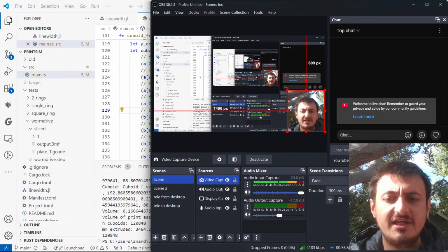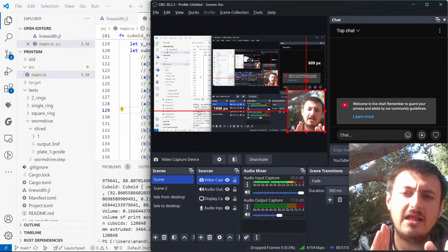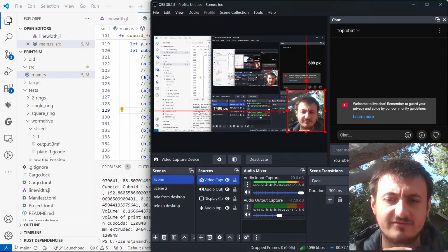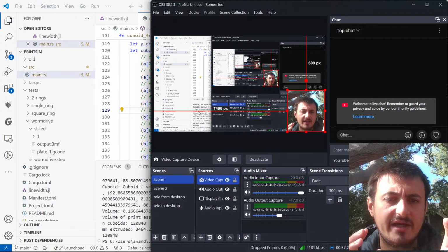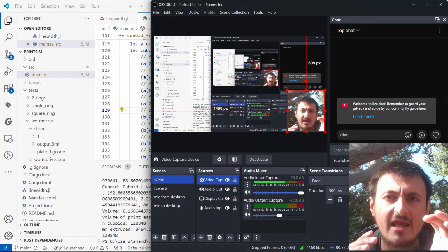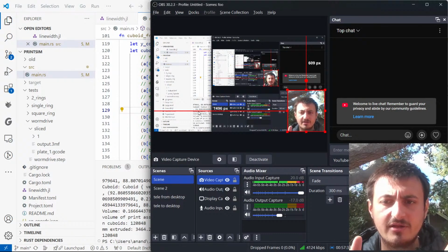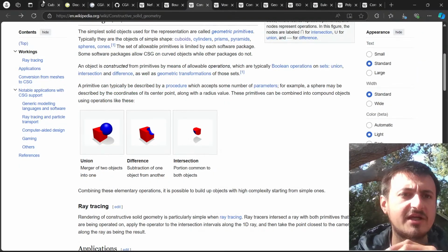We can either build a little boundary representation thing that'll allow us to actually sweep, which is the next step and will take a while, or we can represent an approximation of the model with just CSG, constructive solid geometry. We can add anisotropy to our models by, instead of using a rectangular cuboid, taking the union of two cylinders and the rectangular cuboid.